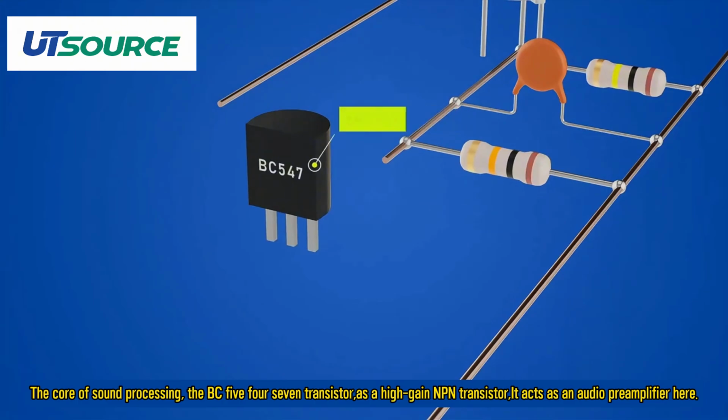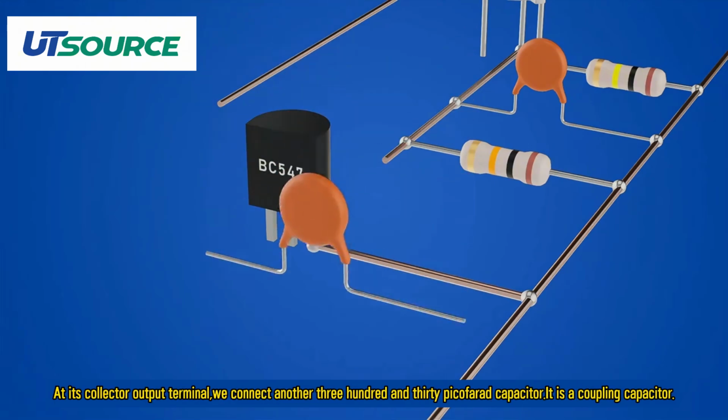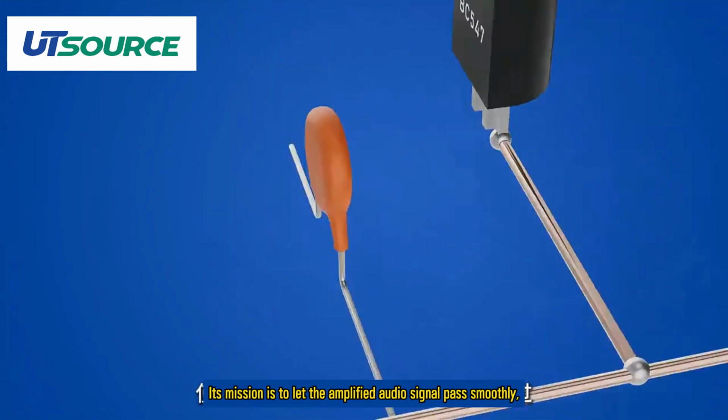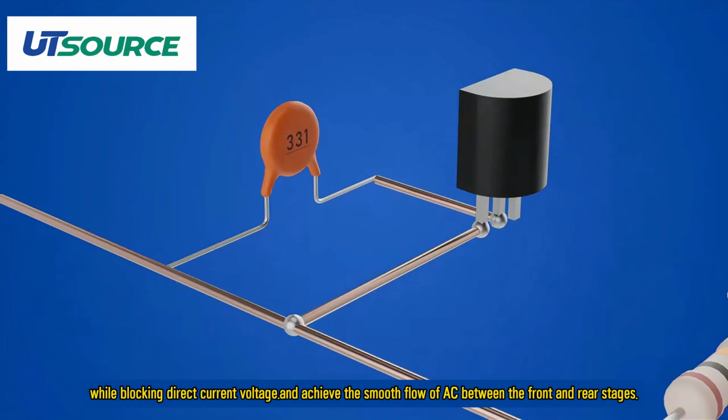preamplifier here. The weak sound electrical signal will be significantly amplified here for the first time, ready to be loaded onto radio waves. At its collector output terminal, we connect another 330 picofarad capacitor. It is a coupling capacitor. Its mission is to let the amplified audio signal pass smoothly, while blocking direct current voltage, and achieve the smooth flow of AC between the front and rear stages.